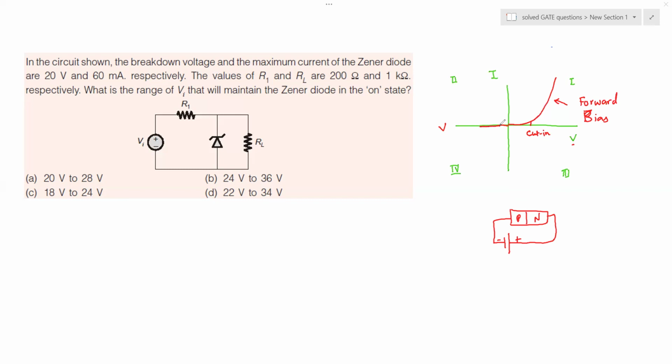That is called leakage current. And suddenly at a specific voltage, which we call V equal to VZ, this current suddenly rises. You can see that. Rather, I would like to draw this in this fashion. There is this steady current, and we can see that there is no slope in the ideal situation.